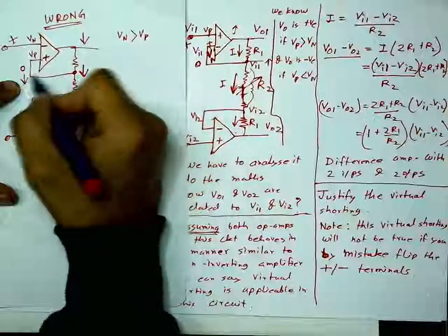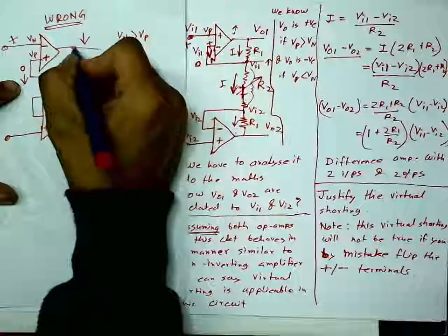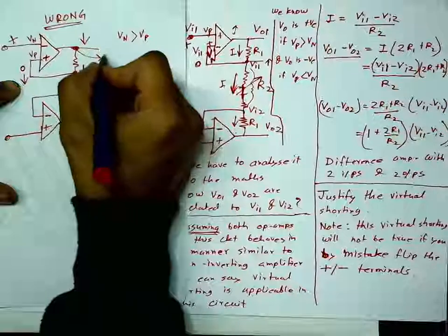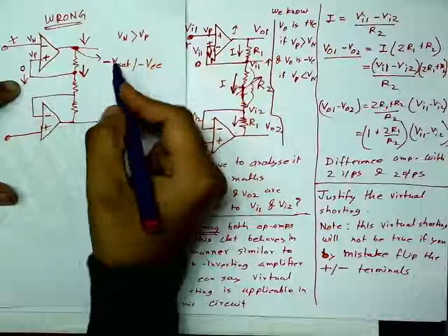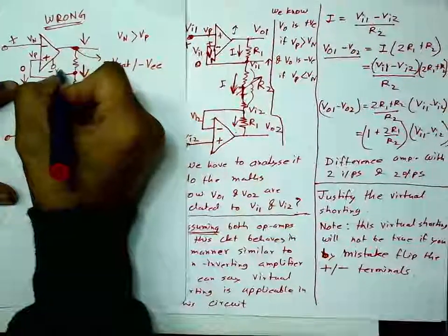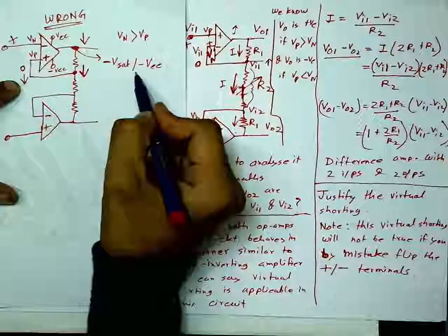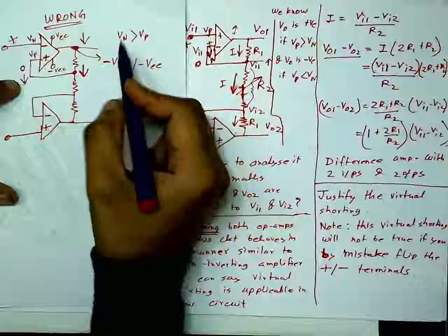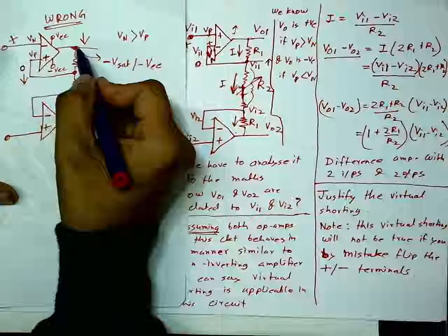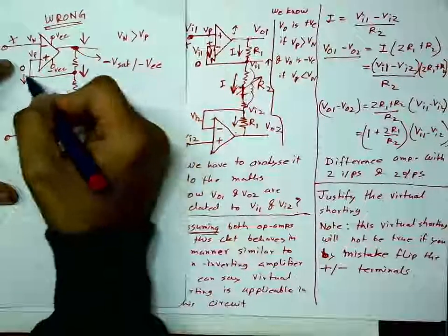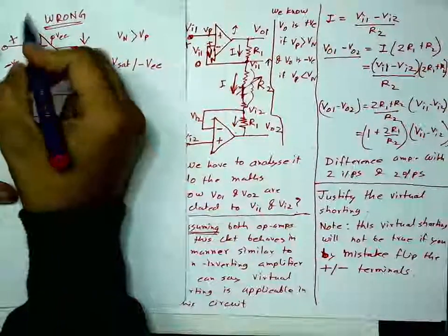This point will further go down, this will be further negative, and this process will continue until this point goes to saturation. This will go to minus V saturation or minus VCC. If this is my minus VCC and this is my plus VCC, the power supply, this point will go to the saturation value, highly negative, so this point will be negative, whereas this is positive.